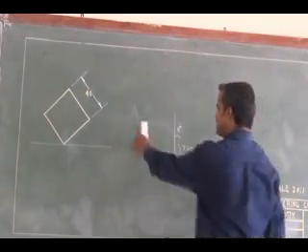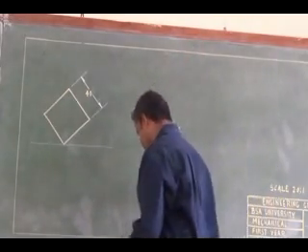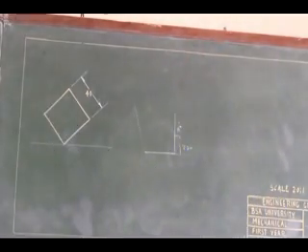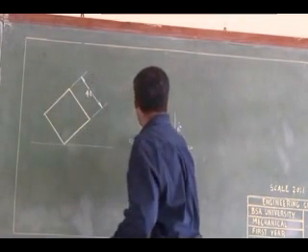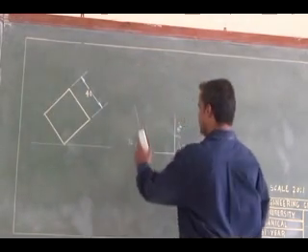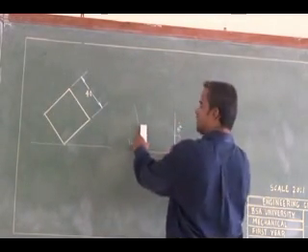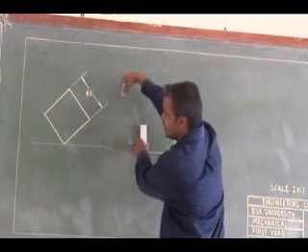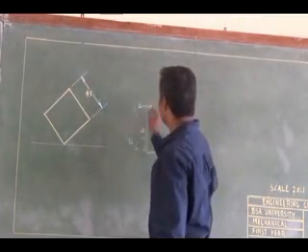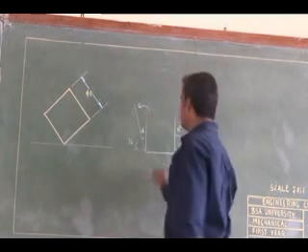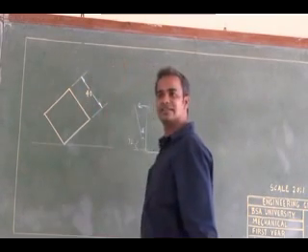Listen. Similarly this side, this is 72 degrees. Outside angle is 72. So what will be this angle? 18 degrees. So I can have my drafter here. Drafter will be like this. The vertical scale I can tilt to 18 degrees to the negative side. Right. So using that scale I can draw this line.